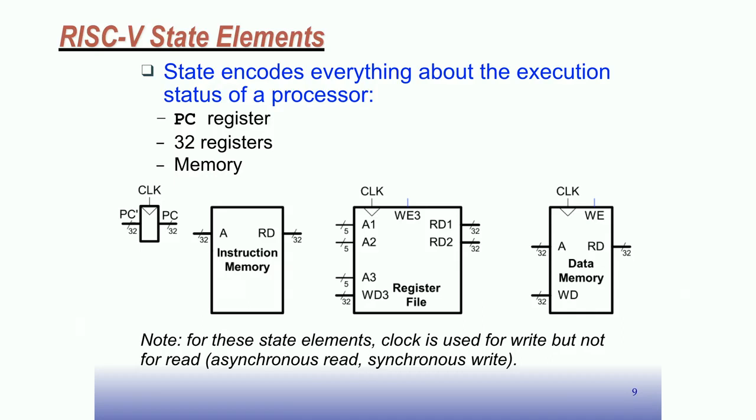The state is, we're going to have a program counter. For that, we're going to have a register that every time we execute an instruction, we're going to increment the program counter to point to the next instruction in memory. Occasionally, we won't just increment it. We'll put a different value in it based on the branch instruction or the jump instruction. Right. We have the instruction memory that's going to hold the instructions. That's a read-only memory. You put an address in, you get data out. The data out, in this case, will be a 32-bit word that represents the instruction that we want to execute.